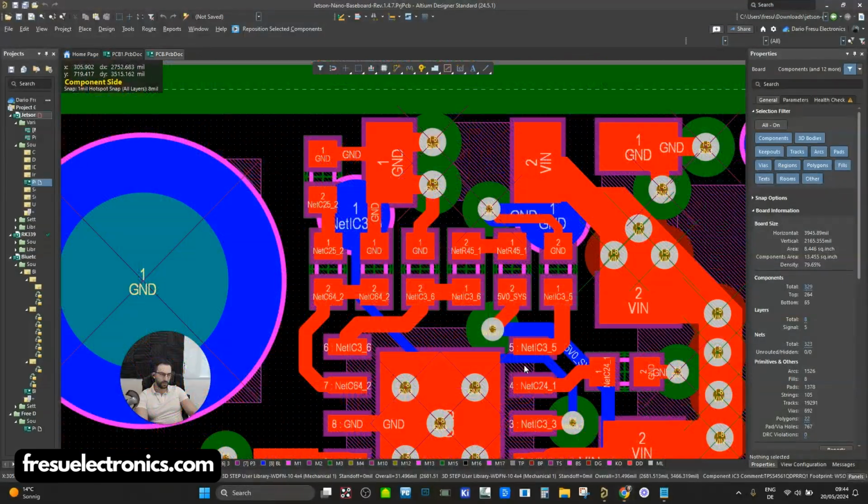So one way that we're going to achieve these goals is by choosing the right decoupling capacitor strategy. And we have to think, first of all, what are the functions of the decoupling capacitors? We have two main functions: one, to reduce the dependency of one integrated circuit on another, and the second is to reduce the impedance between the power and the return reference plane.